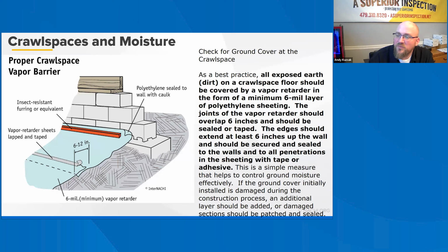Many agencies are unwilling to endorse closing vents year-round due to common moisture problems. Soil type and groundwater level influence moisture conditions, and crawl space can be designed as a short basement with slab floors, generally less susceptible to moisture. The main distinction between unvented crawl spaces and basements is accessibility and likelihood of noticing moisture problems.